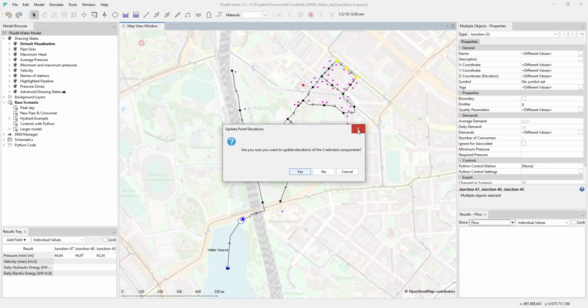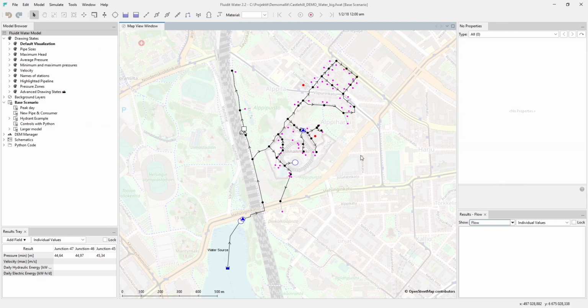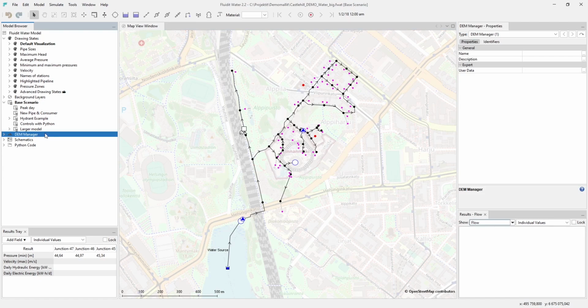In addition to actual tools menu, there are lots of GIS and model editing tools available directly in the map view. Cursor's X and Y coordinates are always shown in the low right corner of the software. If the user holds down Alt key, also Z coordinate, elevation, is shown. This naturally requires that elevation model is set up.